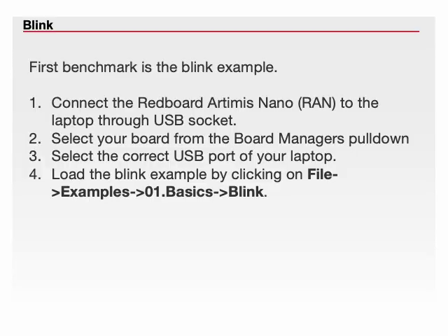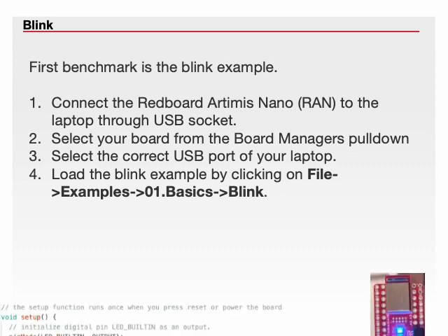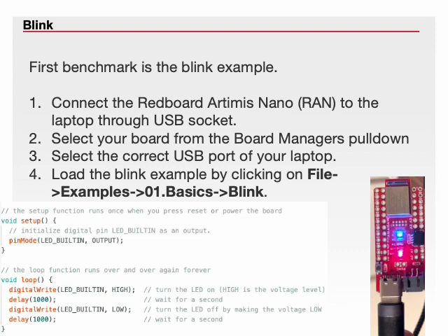Most Arduino boards have an onboard LED and we can control this LED. For that, we need to perform the following steps. In general, you can use all examples using the following steps. Connect the Redboard Artemis Nano to the laptop through the USB socket here.